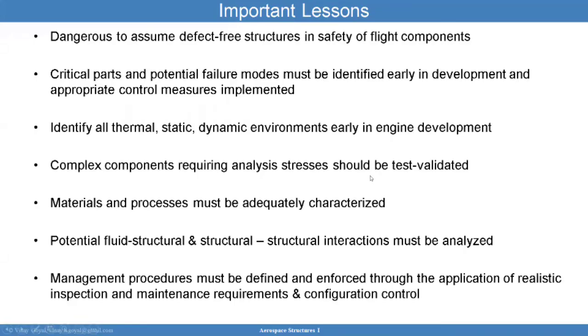Materials and processes have to be adequately characterized. You also want to make sure that we have the fluid-structure and structure-structure interactions well characterized. So the fluid is going to interact with the wing, for example. We want to make sure that that's fully characterized. In a launch vehicle, you may have the fluid inside a tank slosh, go back and forth, and interact with the structural modes of that stage tank as the launch vehicle is flying.